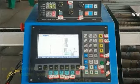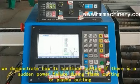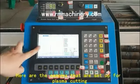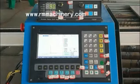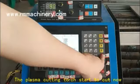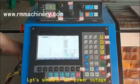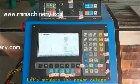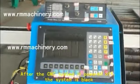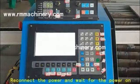Below we demonstrate how to continue cutting if there is a sudden power failure during flame cutting or plasma cutting. Here are the samples that are set up for plasma cutting. The plasma cutting torch starts to cut now. Let's simulate the power outage. After the CNC system is powered off, the system is black. Reconnect the power and wait for it to power on.